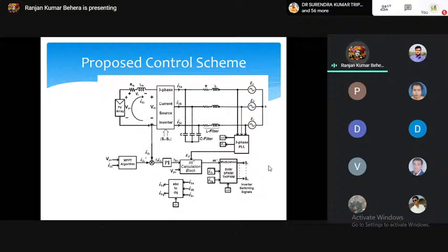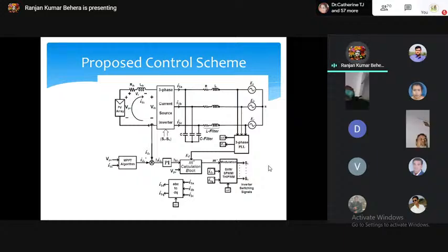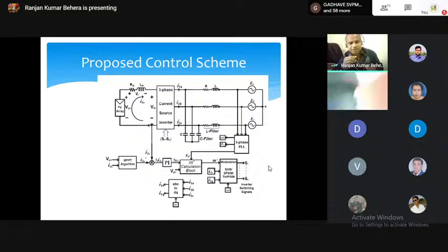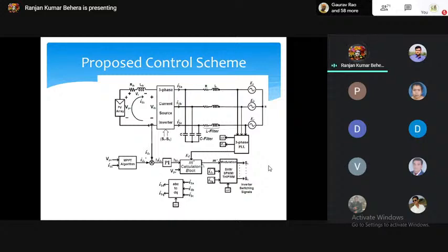So mainly we use this for synchronization. You get the information of the angle at which you want to inject the voltage. That is the most important thing, at which angle you want to inject the voltage, and you get exactly that from the phase information. After getting this, you have a modulation block, and an ABC to DQ, 3-phase to 2-phase, 2-phase to 3-phase transformation.